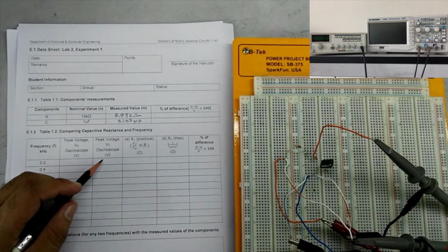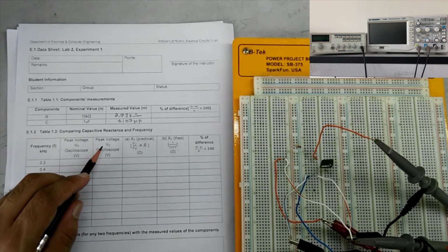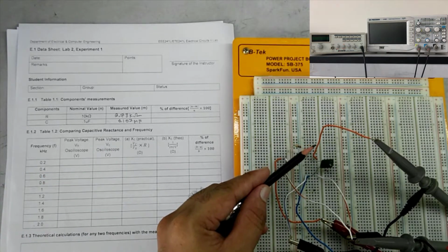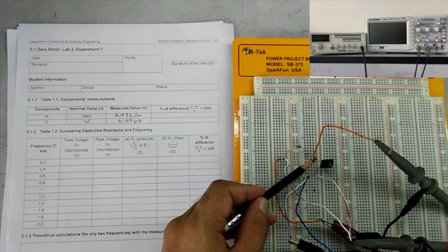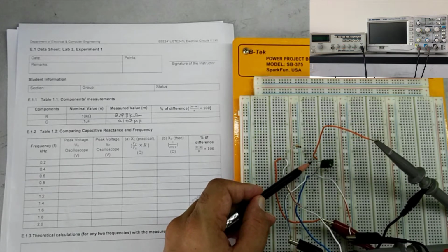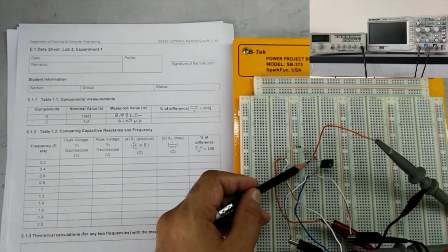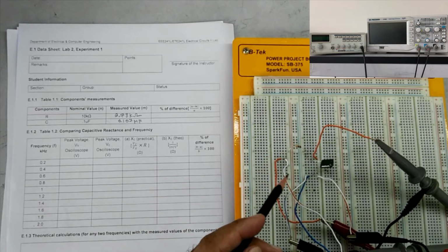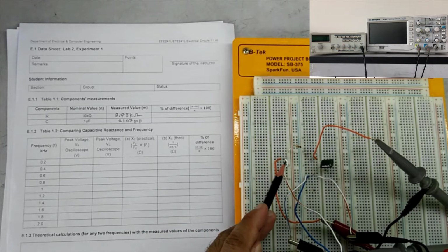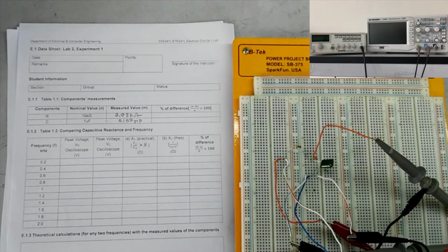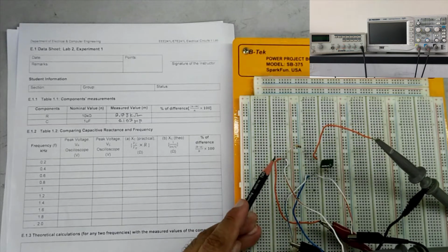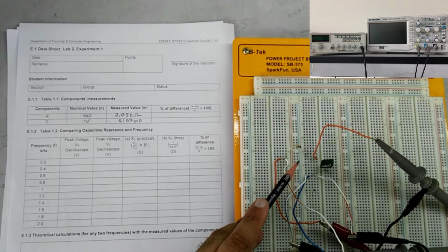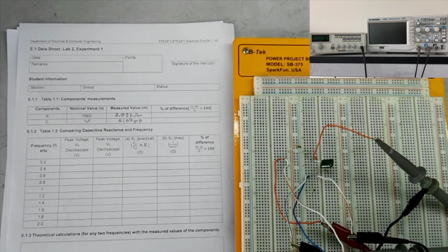Channel 2 is attached to node B, which will give us the voltage drop across the capacitor directly, because channel 2 is connected to node B and the capacitor is connected between node B and ground. So channel 2 is actually going to show us the voltage drop across the capacitor, and resistance is connected between node A and node B, which we will have to find by subtracting the voltages of node A and node B, which we can do by subtracting voltage of channel 1 and voltage of channel 2.